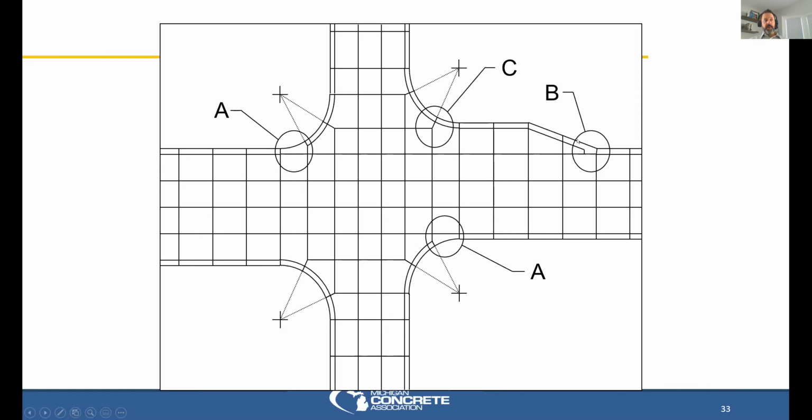At this taper area, we do similar to A in that we bump out the curb and gutter profile so that that gutter pan absorbs that little triangular chunk, and we don't have a constant curb and gutter profile. Again, slip forming first, putting curb on after. You just put the back of curb form in after the lane is in, and you just fill in those areas with concrete.